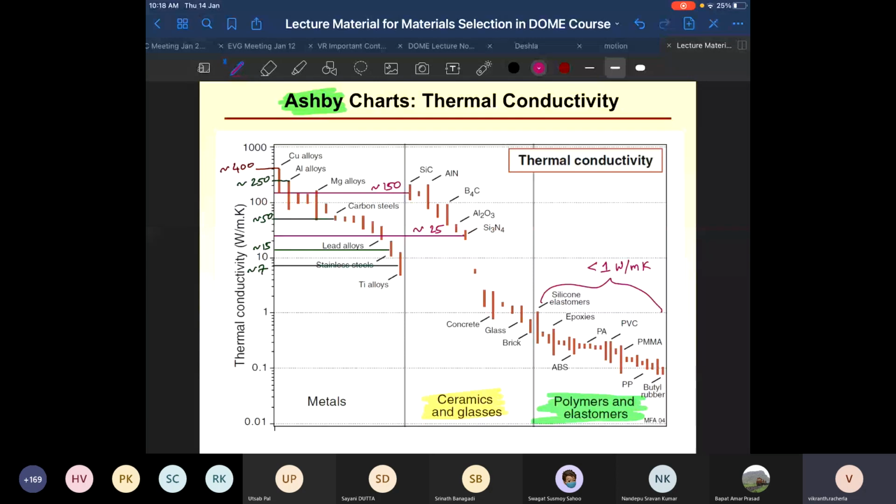And in this particular project, I don't know if you know what lift irrigation is. Basically, you use submerged water pumps to raise the level of water at a particular place, and then use canals which use gravity to transport water from one place to another. This is called lift irrigation. You have to lift the water to a higher level at a spot to basically transport it upstream.